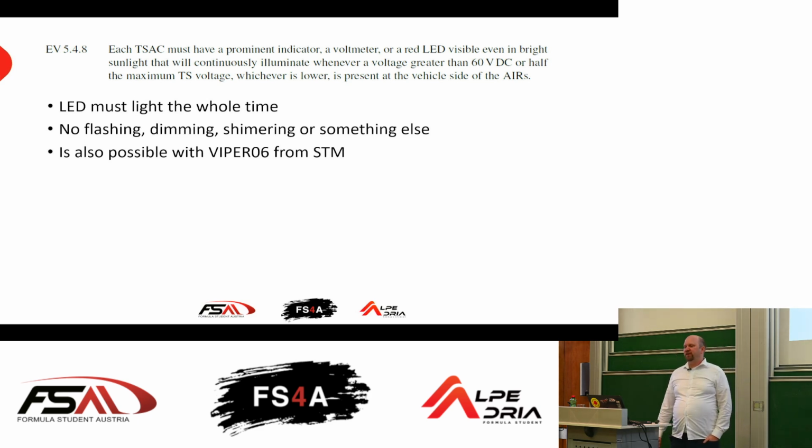For the accumulator indicator, in the last 2 years, it got modern. We saw that the indicator light was flashing at some teams, and you saw clearly it was not intended to flash. The team just built it and it started flashing because they did not provide proper cooling for the chip, the LDO chip or the buck converter. It got hot, turned off because of over temperature, cooled down a little bit and turned on. So we had a flashing of 1 hertz or ½ hertz or something like this.